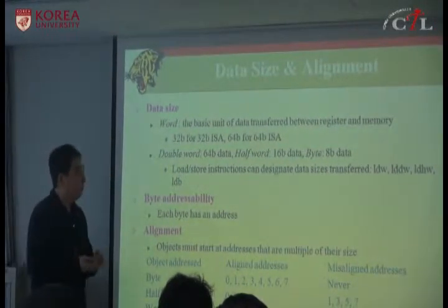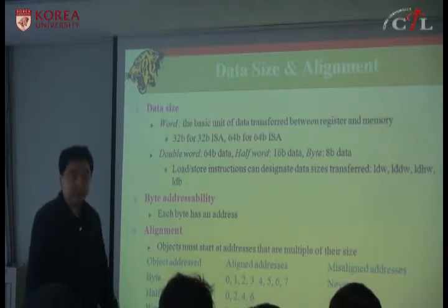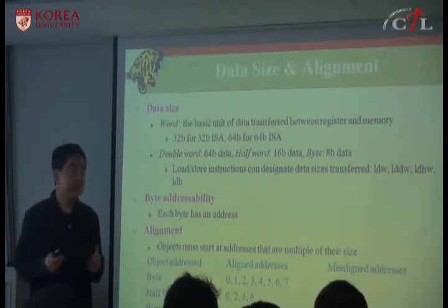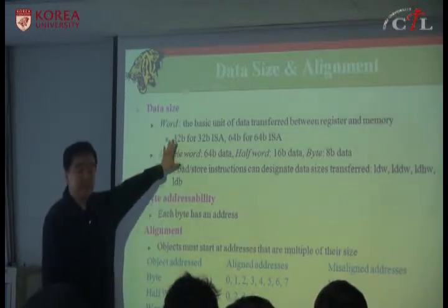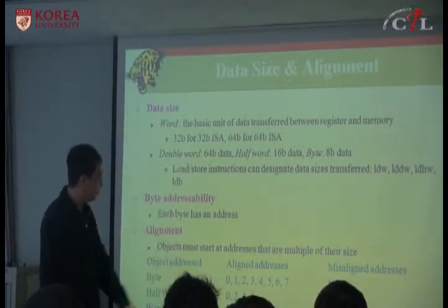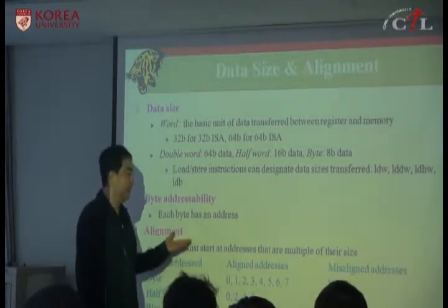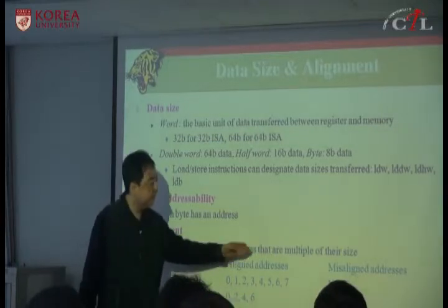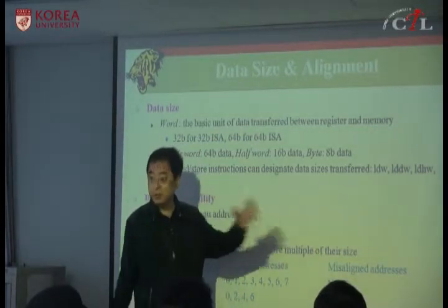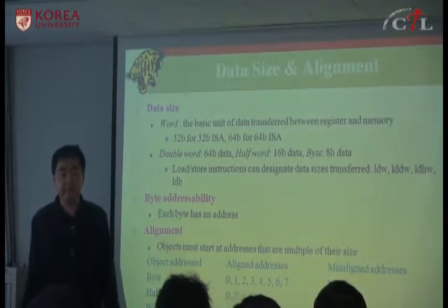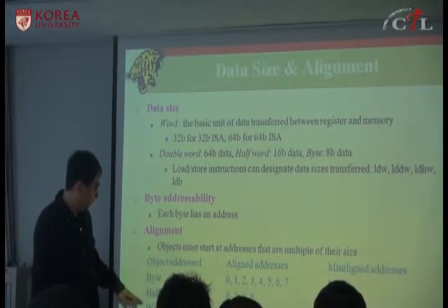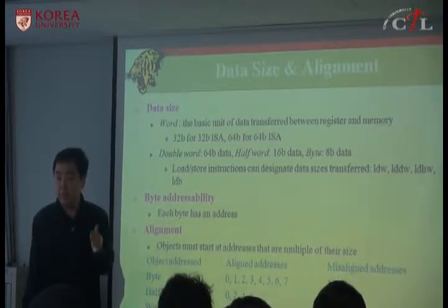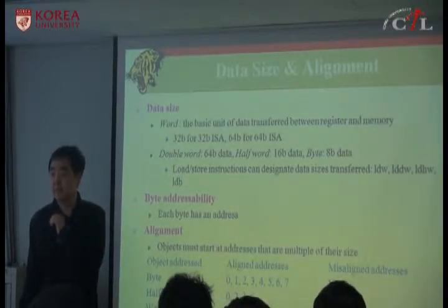And usually in memory, all these objects, meaning data or instructions, can be integer, floating point or character, and should be aligned. Aligned means their starting address should be a multiple of their size. So for integers on 32-bit processors, they should be aligned at the word size, which is 0, 4, 8, 12, 16, and so on.